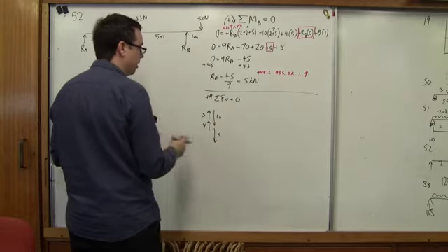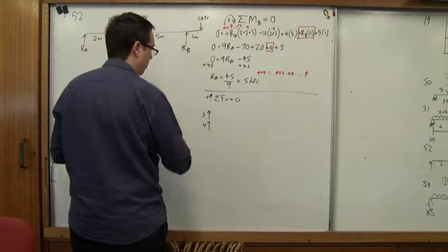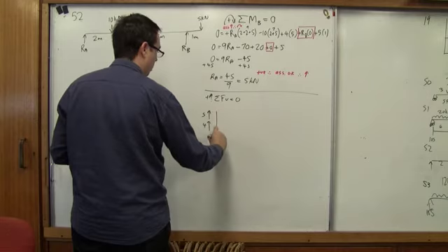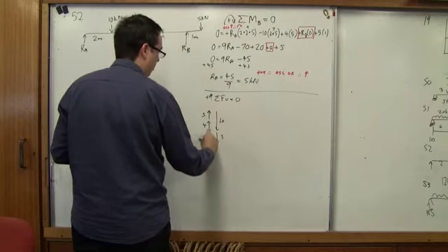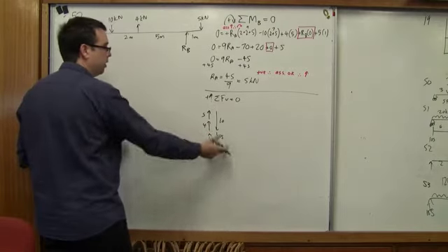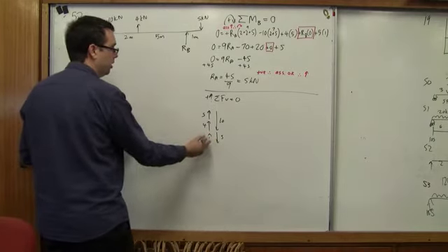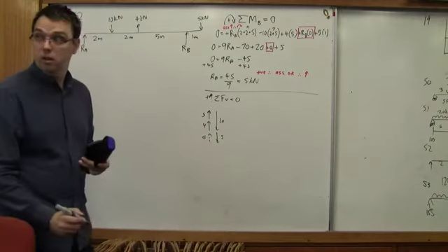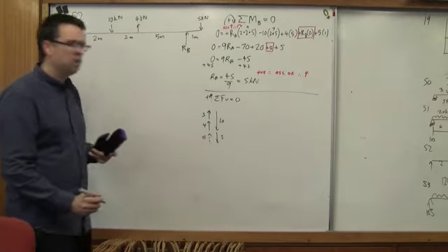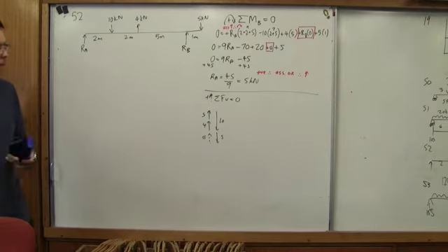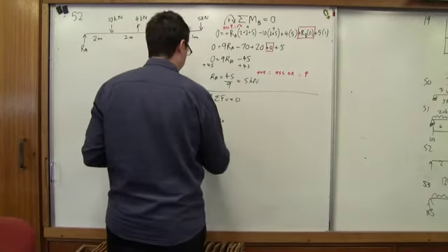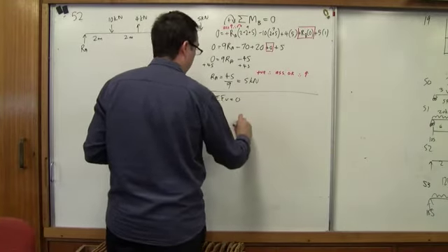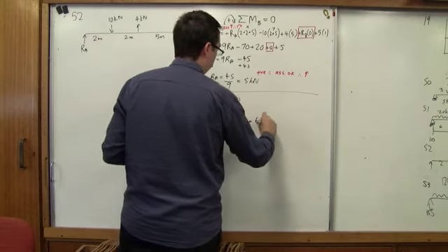Now, I haven't drawn these exactly to scale. I'm going to draw this a little bit better. 10 and 5. What is the missing amount here? Well, this side is 15 and this side here is 9, so it means I need 6 for it to work, yeah? Does that make sense? 15 minus 9. Okay, so that means that we've already found RA, so this one's going to be RB. RB equals 6 kilonewtons up.